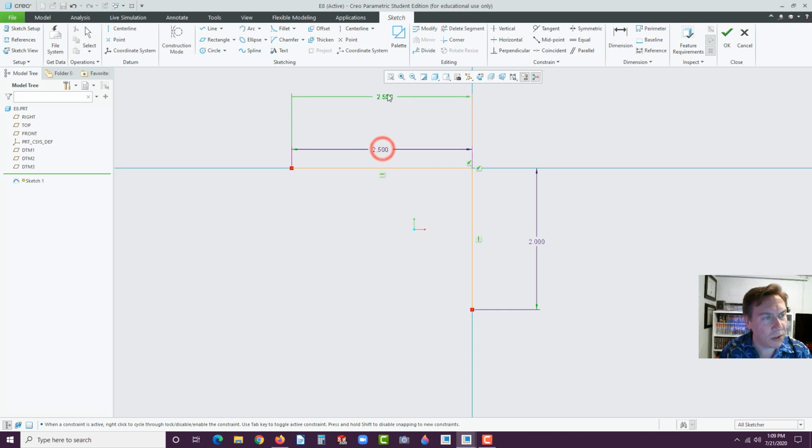Now that we have those, stretch those dimensions out a little bit to make some room, because we're going to add the side of the boat now. So go to the spline tool and get to this vertex on this side, click, and start your way on a journey to the bottom right there, and maybe go about 1/3 of the way. So right about there, click, and now go about 2/3 of the way right here, click, and then finally connect to that vertex at the bottom, click, and middle click 2 times.